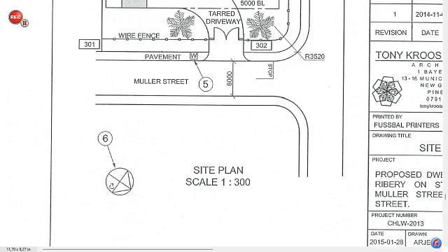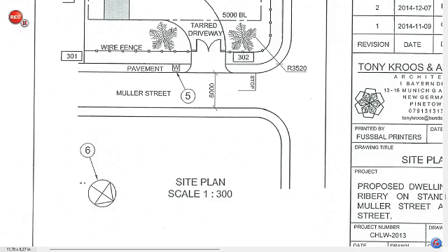Which elevation of the new dwelling faces Gotsi Street? So you are going to find Gotsi Street, which is right here, and then you are going to examine your symbol. In terms of your symbol, this point here faces north, this point at the back south. That will obviously be your west here and your east on this side here. So in between the north and the west will leave you with the northwest